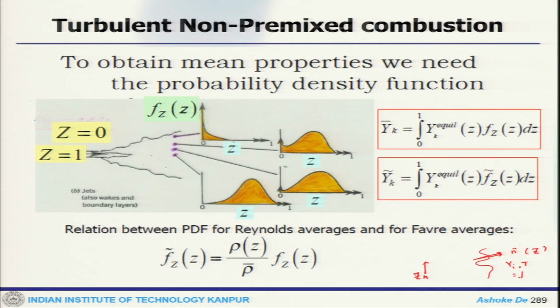That means they are taken as a function of Z and solved there, where the individual mass fraction equations and the variation in the one dimensional front are calculated. It is done at the pre-processing stage, pre-computed, and the information is stored in the form of a table. Now, while we are solving the evolution of the mixture fraction in physical space, using that table we can find out a particular species and temperature.